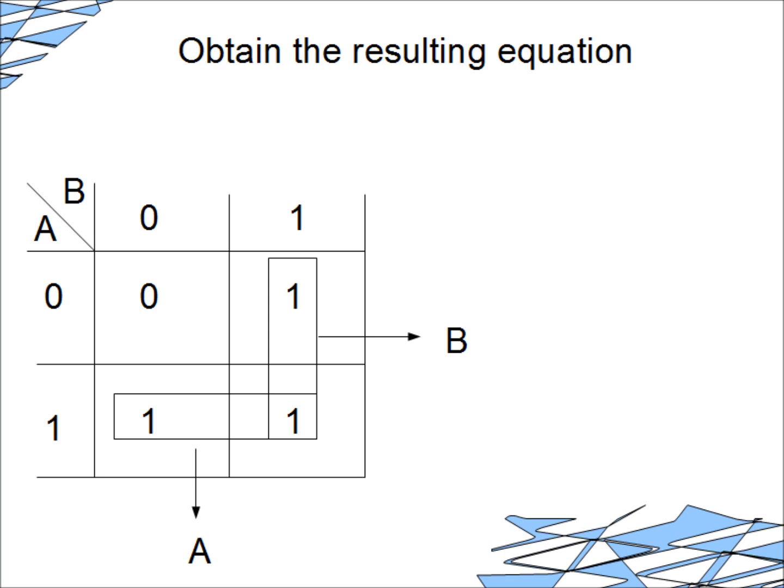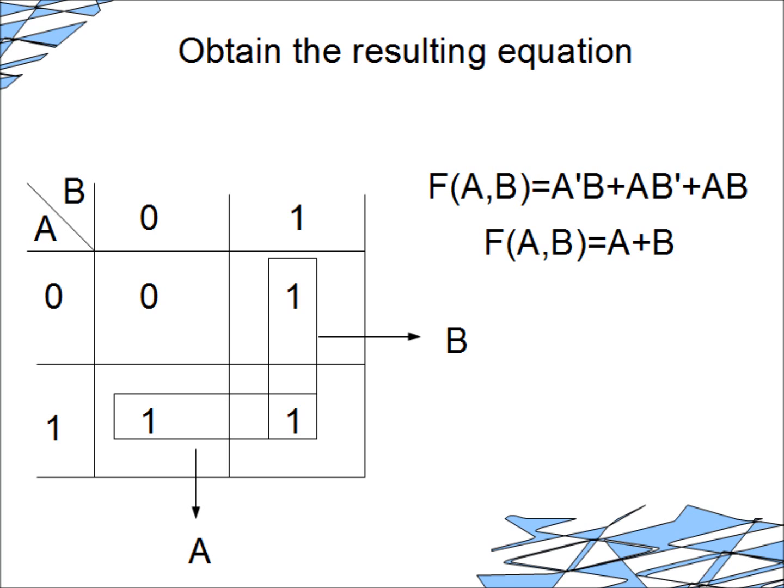Likewise, when B equals 1, we have a 1 at the output, whether A equals 0 or 1. Doesn't really matter what A's value is, but we need to have B as a 1. And we add these guys up, and we get A plus B, or A or B. If either A or B are 1, we get a 1 at the output, which is what this function is supposed to do. And we can now compare it to the original canonical form with 3 terms. Now we've lost a term, and our terms are simpler.